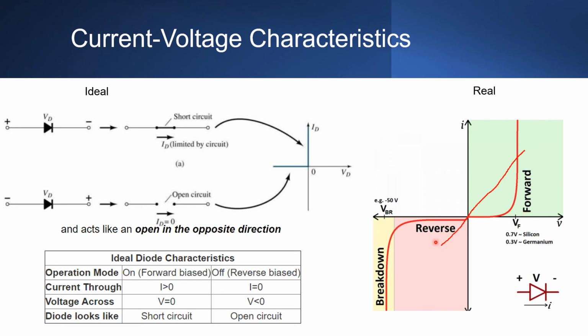While for the reverse bias, this is the off mode of the diode, where the voltage is less than the forward voltage, but greater than the negative of the breakdown voltage. In this mode, current flow is mostly blocked, and the diode is off. A very small amount of current on the order of nanoamps, called the reverse saturation current, is able to flow in reverse through the diode.